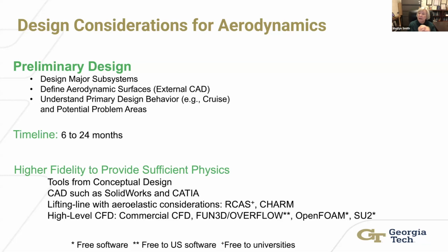Look at this early on because rotors especially are inherently aeroelastic. If you have a wing, that could have some aeroelastic issues, and when they move, when they're not rigid, when they are flexible, that can impact your performance. So again, especially if you're close to your margins, look at those.